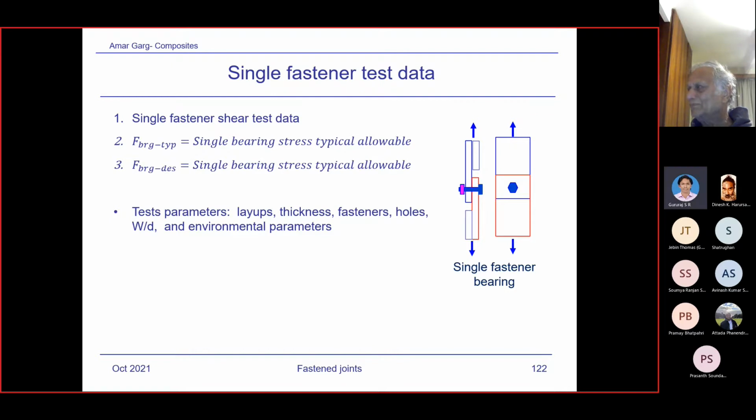So this load sharing is also automatically picked from the analysis, right, sir? Well, load share is normally done by FEM. But sometimes for the fittings, when we are looking at the effect of various parameters, we may do it individually by hand, with two-dimensional or one-dimensional analysis. That is more critical for the fitting. Otherwise, most of the time, load share capability will be taken care of by FEM.